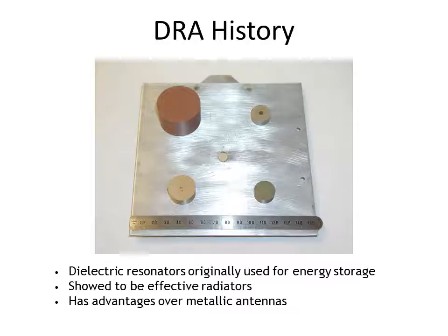The reason for this innovation was a result of the inefficiencies of metallic antennas like the microstrip antenna. At that point in time, wireless communications devices were beginning to use higher frequency ranges. At these higher frequencies, metallic antennas began to experience a large drop in efficiency as a result of conductor loss. When looking at the losses from a dielectric resonator antenna, it can be shown that the main loss is caused by imperfections in the dielectric material used. This loss is very minimal compared to the metallic antenna losses.